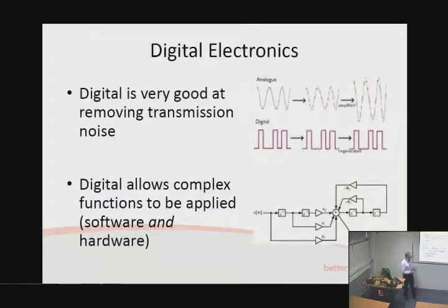So digital electronics is a hugely successful approach to information processing, and there are so many good reasons why. I think the key party trick with digital electronics is this capability: inevitably signals will become polluted with noise. In an analog signal, that noise will tend to build up and up and up. In digital, it's possible to throw away that noise and regenerate and reconstitute the signal as it passes from one area to another. That's a very important party trick.